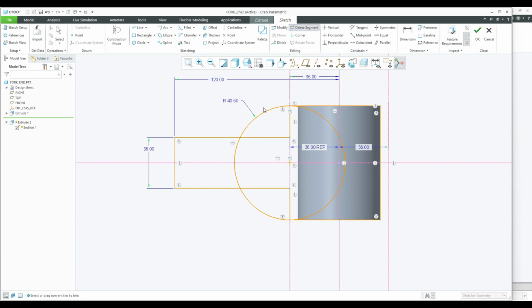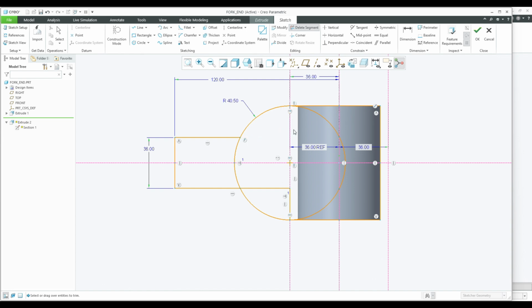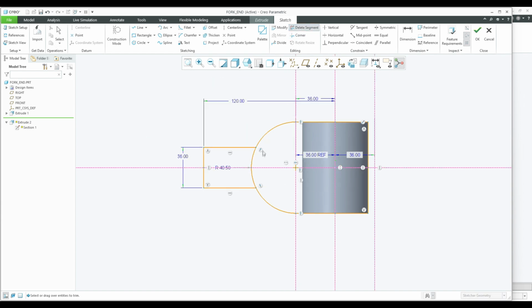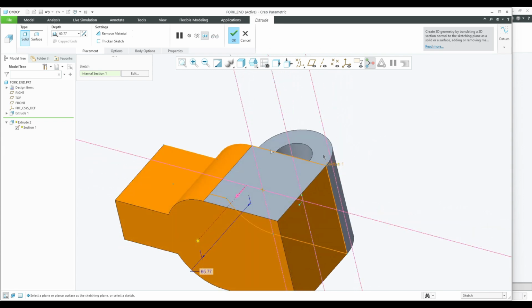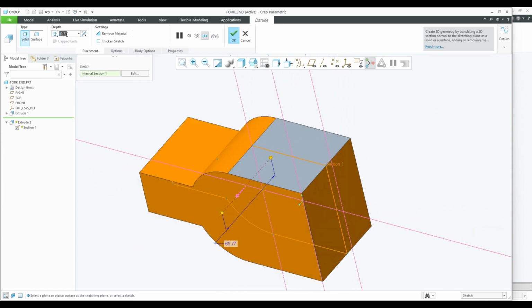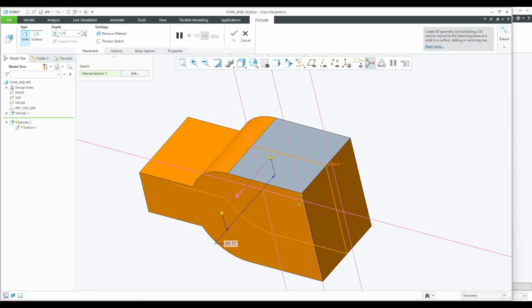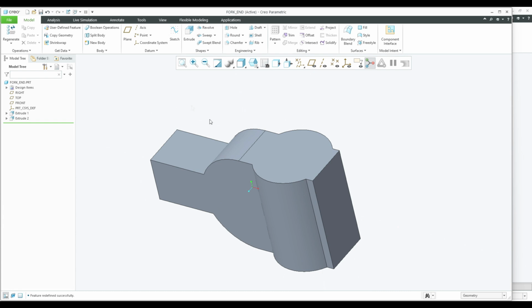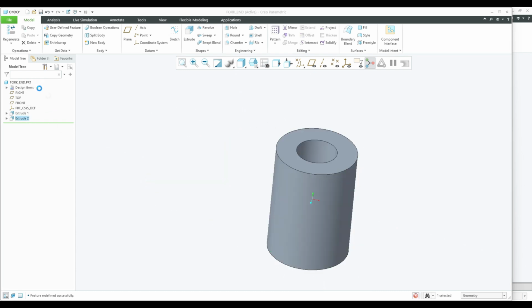So I'm going to delete all the unrequired items. This is not required, this is also not required, these are all not required lines, and this too. So in this condition I have created a line. I'll just click OK, and this extrude also I'm going to make symmetric with the extrusion length of 1.2 into d. I'm getting an extrude at the edge here.